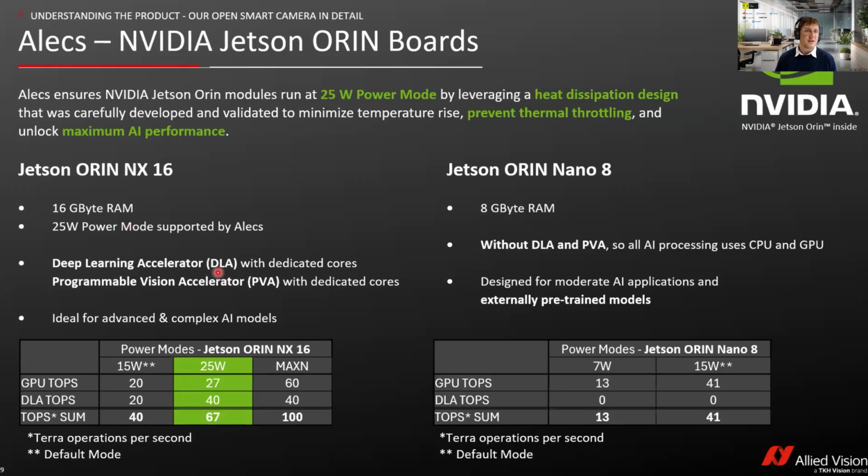The different cores in a Jetson Orin NX 16 are the CPU itself, the GPU, and, only on the Jetson Orin NX 16, dedicated cores for so-called deep learning accelerators, which are cores the customer can directly use to perform their AI algorithms. So you do not need the GPU; you really have the DLAs, the deep learning accelerator cores, to drive your AI algorithms.